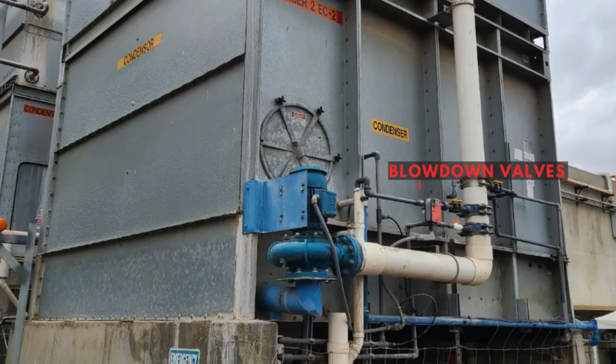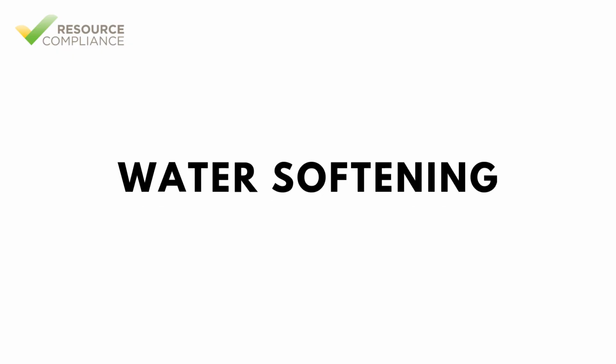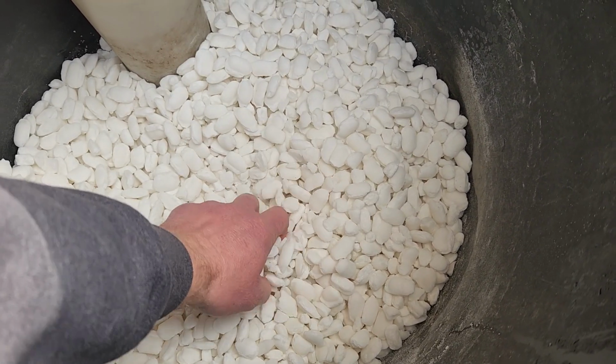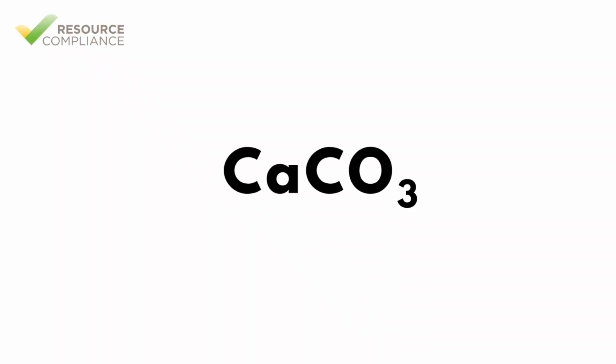Blowdown is employed to remove a portion of the water with high concentrations of dissolved solids to prevent scaling. In situations where chemical treatment is not used, blowdown should be continuous. Total dissolved solids should not exceed 1,500 parts per million. Blowdown rates can also be automated by using sensors that monitor conductivity levels in the water. A water softener can be used to reduce the hardness of the makeup water. A softener accomplishes this by removing calcium and magnesium ions, which are major contributors to scaling. Water hardness should be maintained between 30 and 750 parts per million of calcium carbonate.